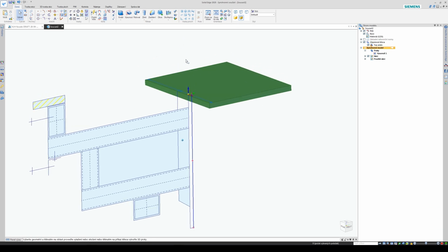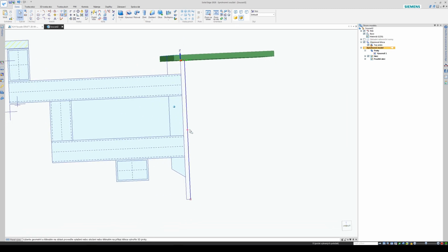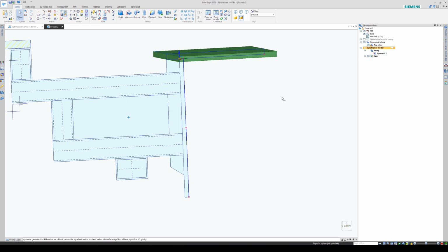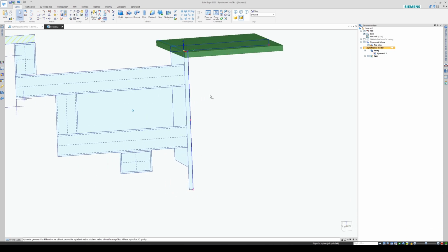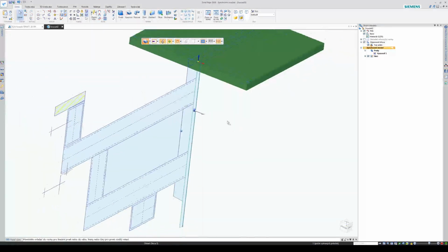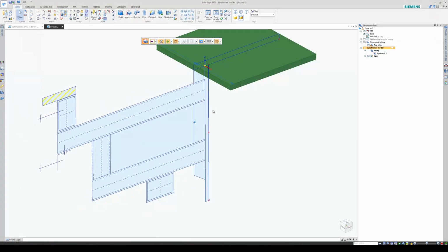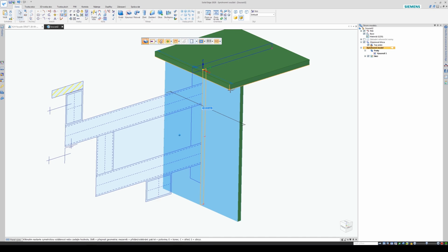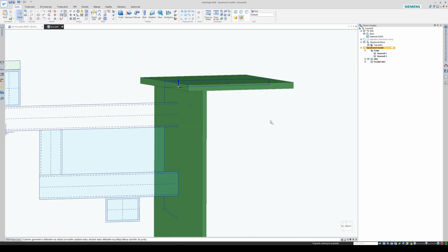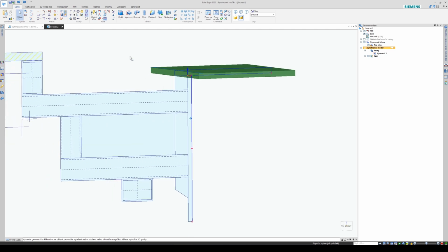Okay, so let's construct this front plate. I need to reuse sketches. If I now make an extrusion, it will be the same object. I don't want it. Just Ctrl Z.